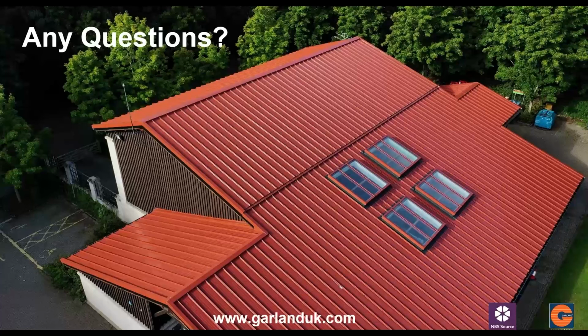So our preferential way that we'd always recommend is having a ballasted system. So therefore there's no penetrative fixings, and this would typically be associated with flat roof applications. And we'd also insist that on the bottom of a ballasted PV system, the feet are either rubberized or there's a sacrificial layer underneath, either of another bit of membrane or a neoprene or rubber mat. That would firstly be our preferential option. But ballast obviously increases load and weight to a roof system. So if it's a refurbishment, it might not be possible.